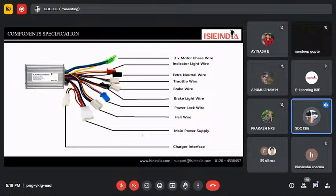When we talk about controller basics, there are 5 basic wires, where 2 wires are given for the battery connections as an input to the controller, and 3 wires are for the output from the controller, which is connected to the BLDC motor. Along with that, we have a lot of other wires, which take commands, like taking a response from the Hall effect sensor wire.